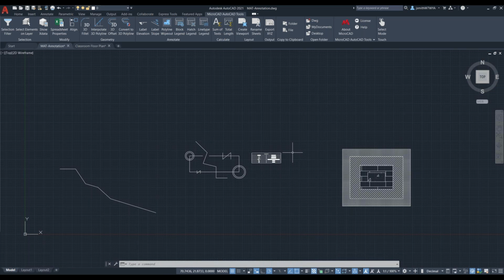And it just takes the guesswork out of adding a new viewport into paper space and not knowing where in your model space it's going to actually show up. It's a very random process. So when you do it this way, it actually lets you select more accurately how your viewport's going to look once it converts over to paper space.